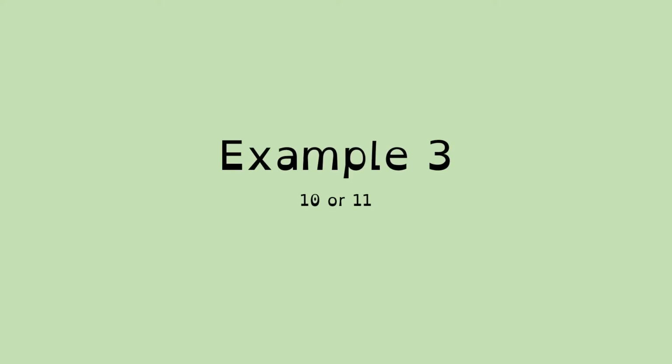Okay, so we're looking at an example that's come through from the previous two videos in this short series, which is that we want to create a circuit which takes a digital input, a decimal number 10 or decimal number 11, but we're going to convert that into binary. And in either of those cases, we want to have a 1 high at the output, and in any other case, we don't want to have that. So we translate that to binary 1010 or 1011.